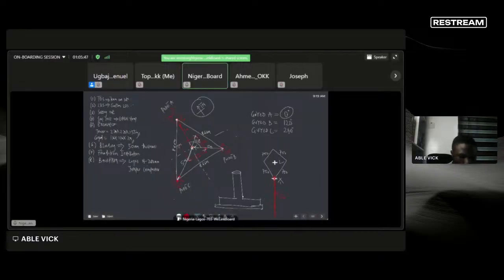You install your tower foundation in a trench, and you want to start your backfilling. Because of this base plate here, the first layer can be 400 mm. But after this first layer, the next layer has to be 200. So you keep on doing like that until you get to your final elevation.